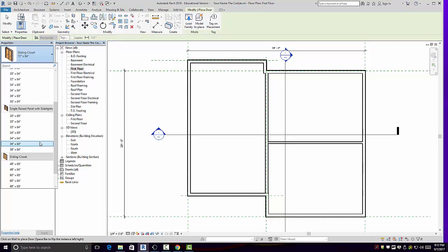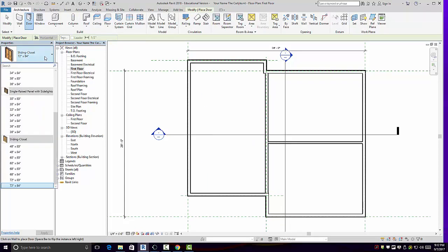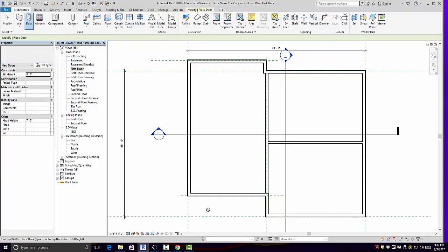So I'm going over here on the architecture tab, pick a door. They're families. They insert in the wall. So I'm going to pick one that's commensurate with size. It's 36 by 40, 8'4", right? And that one has a side light on both sides. And I just kind of placed it in a wall, and I'm looking at some temporary dimensions.